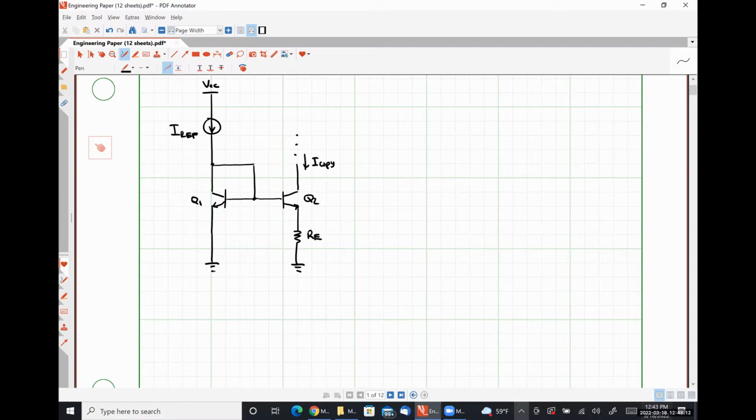Current through the resistor biased the rest of this network. And this particular topology allowed you to get away with using a reasonably small resistor here and a pretty dang small resistor here in order to get the same results as something that would take hundreds of kilo ohms of resistance to generate. Okay. This is actually the current source that's used to bias the differential pair stage of a 741 op amp. Even to this day, what they used to do.